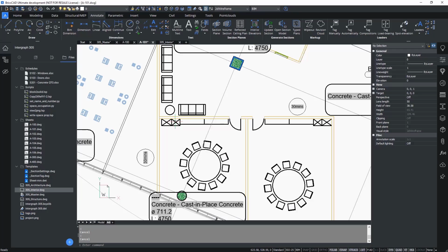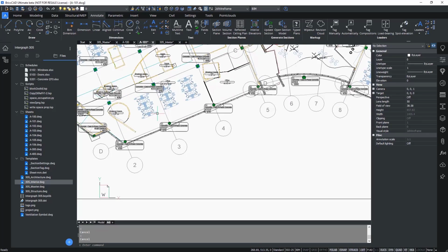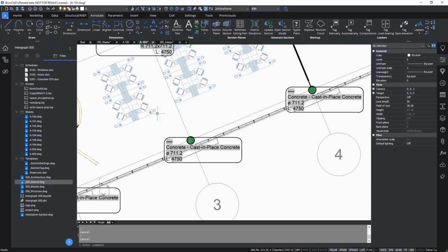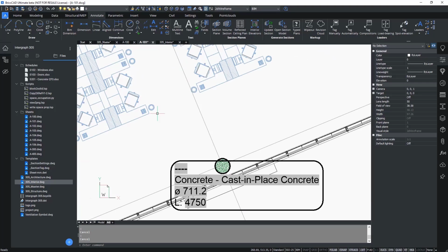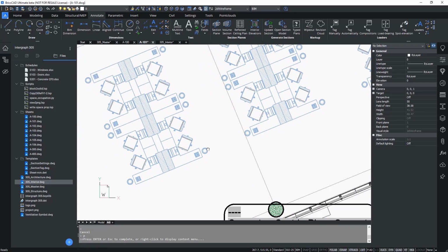In V22, we've improved our annotations to read those field values I demonstrated too. If you would like a parametric annotation to reflect the right field value and add some notes at the end of the text, we have what we call informally Impromptu Tags, which exist as part of the mleader function. Any object that you point to can be any form of a BIM entity, so you are not restricted by the usual elements like walls, slabs, or columns. We can add fields which display names and number. For example, I am now pointing this to a chair.